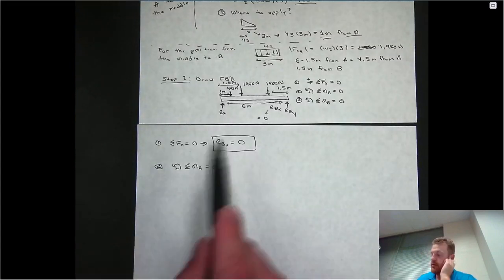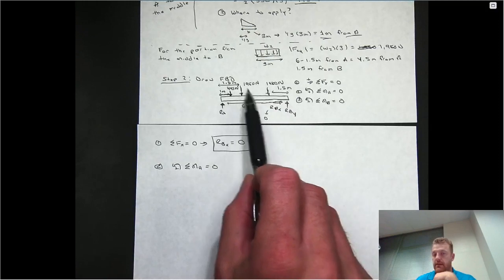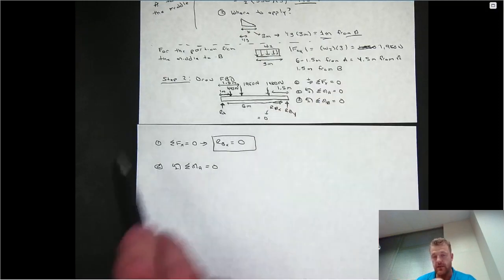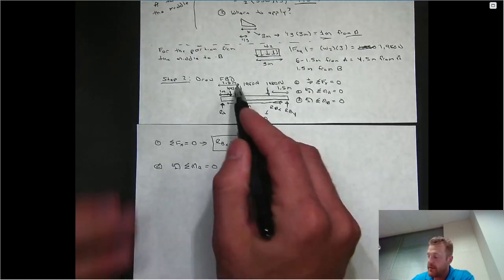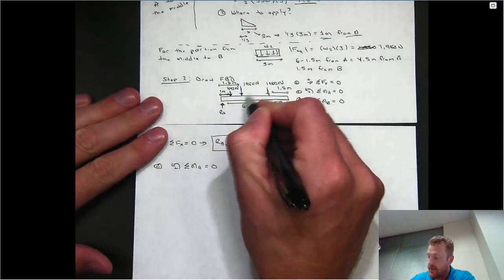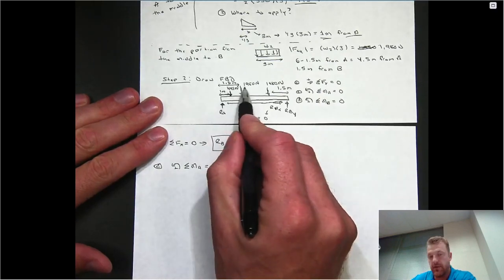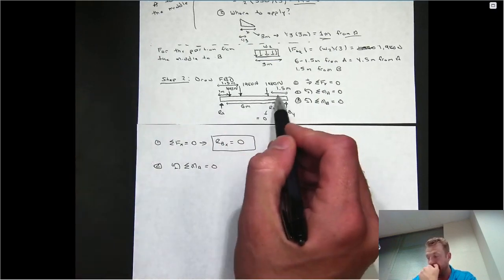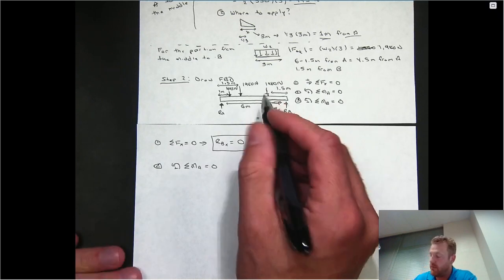So let's actually compute what this would be. As we justified earlier, all three applied loads are going to tend to induce a clockwise rotation, so they're all going to be negative. And the perpendicular distances, since they're all vertical, are also pretty easy to see. Relative to point A, this is 1 meter away, this is 1.5 meters away, and if the entire beam is 6, and this dimension is 1.5, it's going to be 4.5.